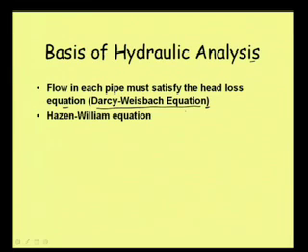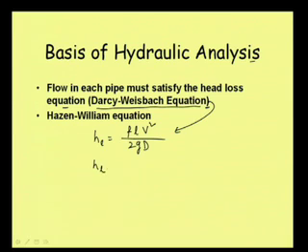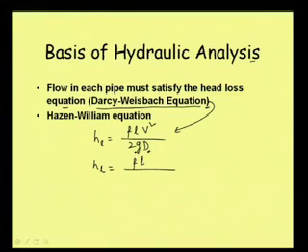Now, considering that, head loss HL is equal to FL V square by twice G D, that is the Darcy-Weisbach equation. Starting from this, F is the friction factor as we know, L is the length of the pipe, and V is the velocity of flow. Of course, we talk about average velocity when we talk about velocity of flow in a pipe. At the central line, the pipe flow velocity will be more, but we are talking about the average velocity in the pipe. And D is the diameter of the pipe, G is the acceleration due to gravity.